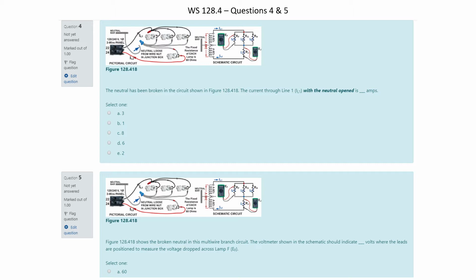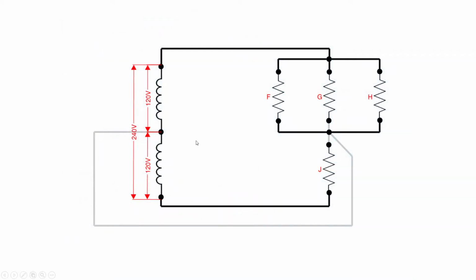So let's really break this down. So let's just kind of look at this whole. Both these questions relate to the same circuit. So I've kind of redrawn this circuit in a more direct way we can kind of understand. So we have 4 equal loads here. We have 3 connected to this phase. We have 1 connected to this phase. And then we have a shared neutral going back. So what's the current flow look like in that circuit? Normally should look like that. So in this case, both circuits have 120 volts applied to all the loads, all the elements. Everything's great, running good.